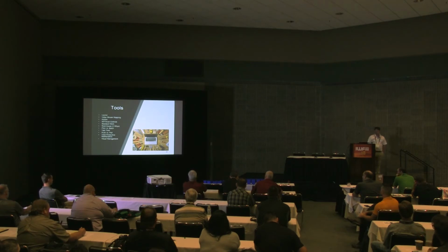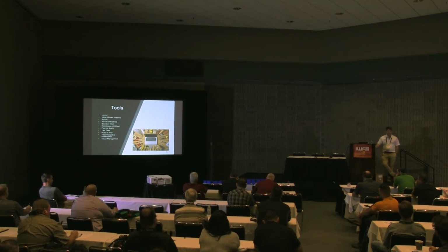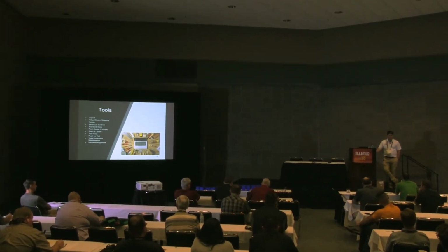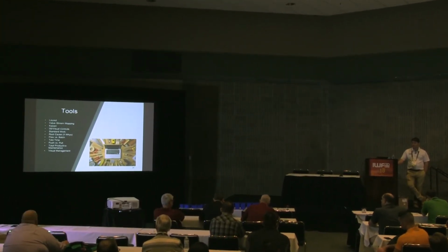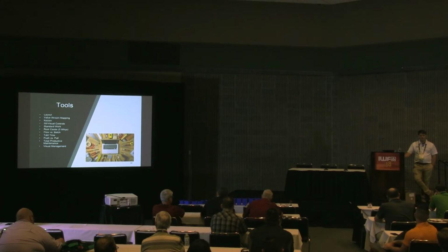Takt time or flow versus batch. How many use single piece flow? And how many batch? Well, if we're going to make 100 of these a month, we might as well make all 100 at the same time. Maybe it makes sense depending on what your batching processes are, and maybe it doesn't. Single piece flow can provide significant improvements in delivery time. You may incur more changeover on equipment, which can be reduced as well, but delivery to the customer improves, which means what? You get to bill more, right?